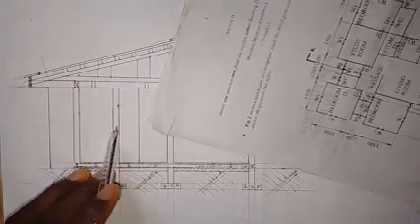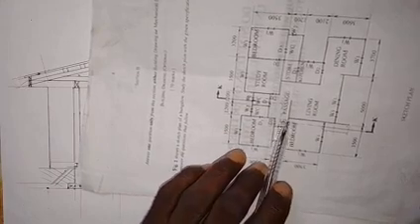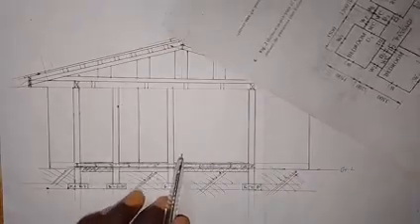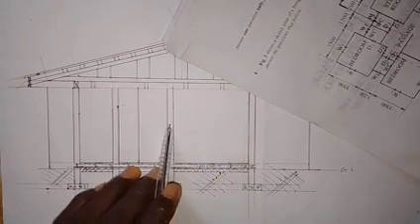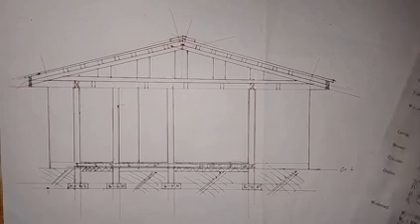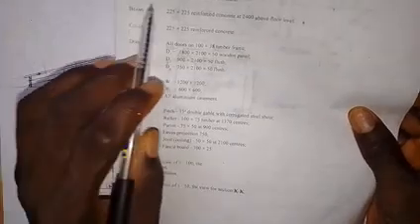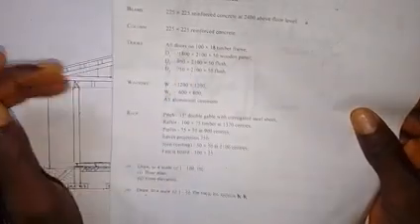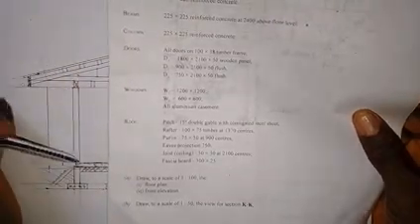Then we are going to see this door here, okay? So it also cut this door within this wall, that is the wall that we have here. So let's see how that construction goes. So then for the lintel, we have 225 by 225, but they didn't give us the distance of the lintel from the floor.